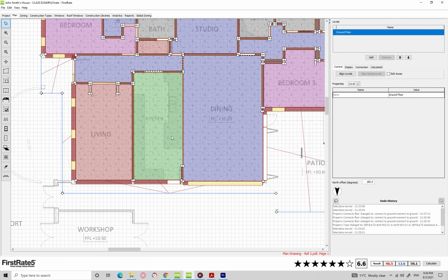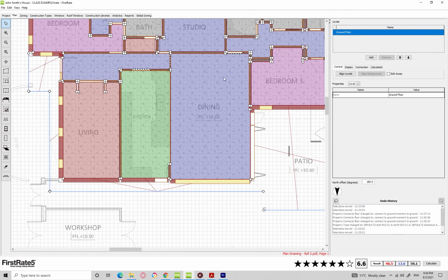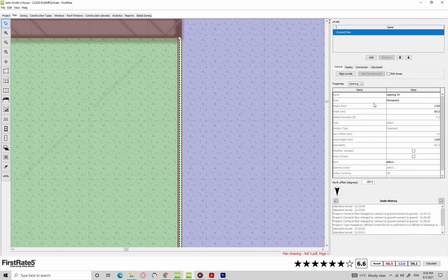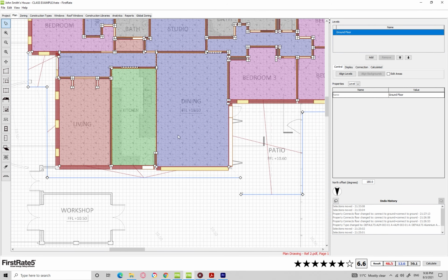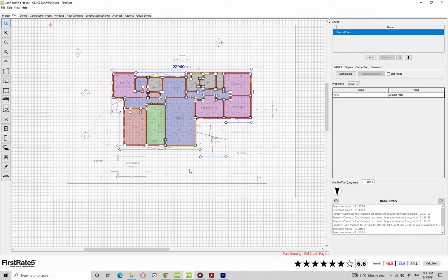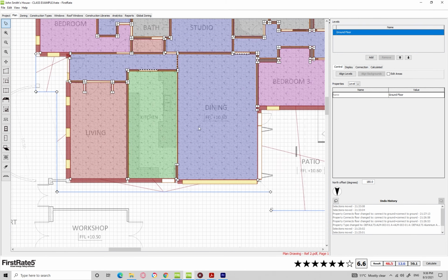During the rest of the day, the sunlight will be hitting this wall here, and the eave is blocking some of that as well. Meanwhile, the kitchen is open over to this dining area. It's a bit hard to see, but I have shown a permanent opening between these two zones, and the kitchen forms part of this dining. The dining actually receives a lot of sunlight. You can see here this corner will receive direct sunlight from the north, and that would obviously enter into that kitchen area.